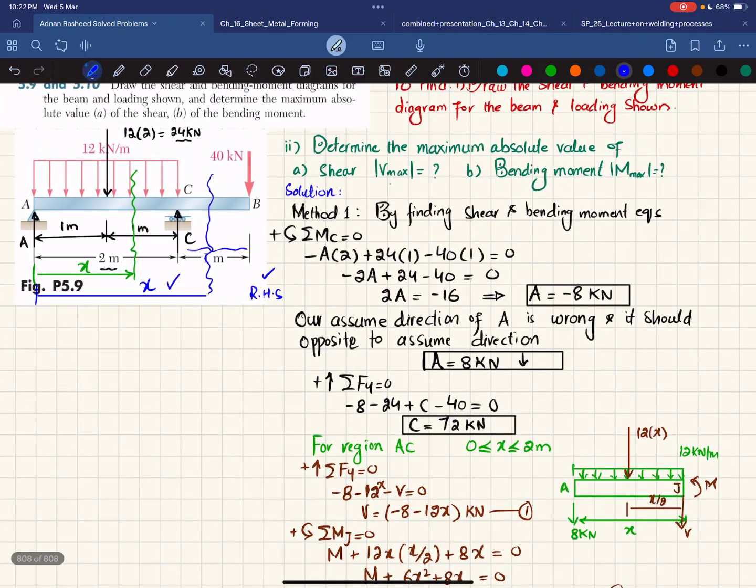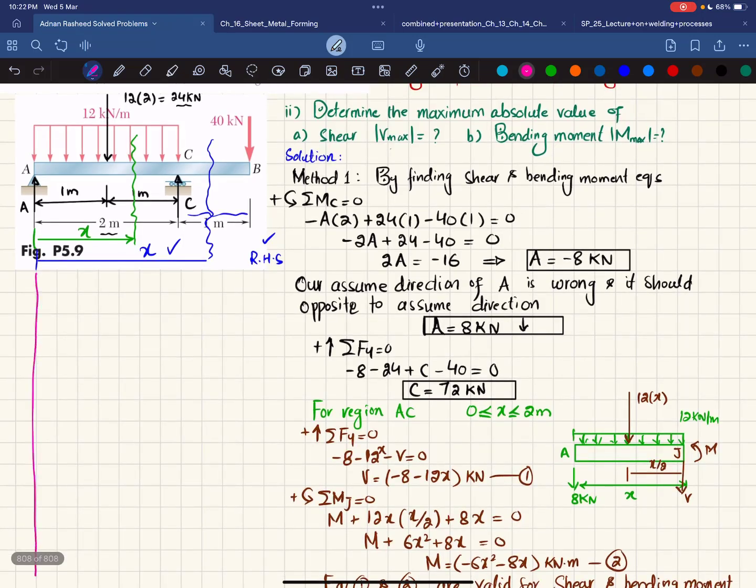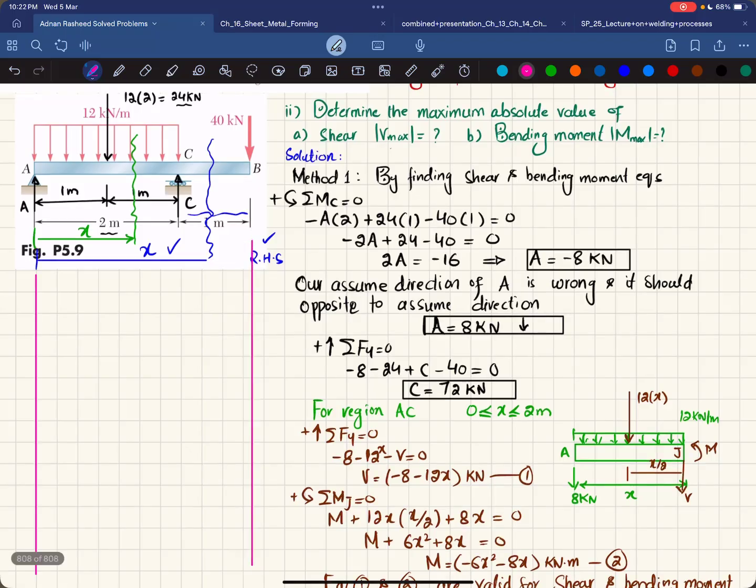So what we will do is take a vertical line from the end of this beam. This is the end line of this beam, and first we will draw the shear force diagram. For the shear force diagram, I will draw a horizontal line that represents x, and x is in meters. On the y-axis you have shear force having unit kilonewton. Let each division be of 10. So 10 kilonewton, 20, 30, and this is your 40. Same is minus 10, minus 20, minus 30, and so on.